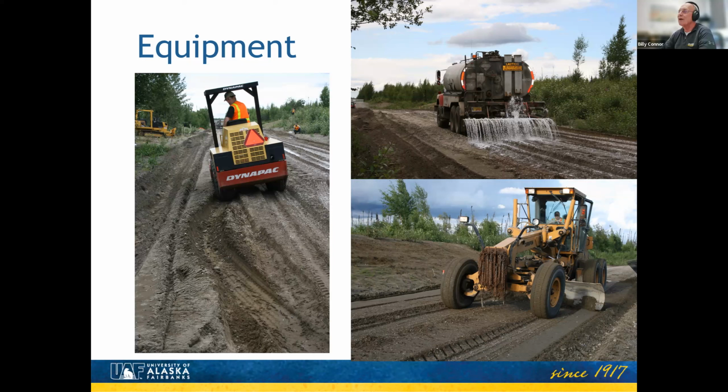We treated the top 6 inches, so we put a pretty heavy layer down. But you can also put it down with gravels or sands, and of course silts. It will work as well. So it's really tolerant to the type of material. All you need is a water truck, a grader to shape it, and a compactor to compact it, and you can put it down, and it will give you a surface much like pavement.